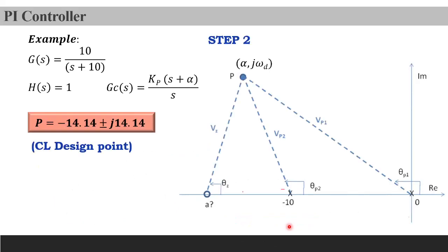And then we will sketch the root locus in step 2. So now we know that if we multiply these two, so we would have one pole at S. So all right, so GC gets multiplied with GS, right? These are both part of the forward path gain and they are cascaded together, so both would get multiplied, and we will get s into s plus 10 in the denominator, which indicates that one pole is at s equals to 0 and one is at s equals to minus 10, right? So we have this minus 10 and 0 location poles.